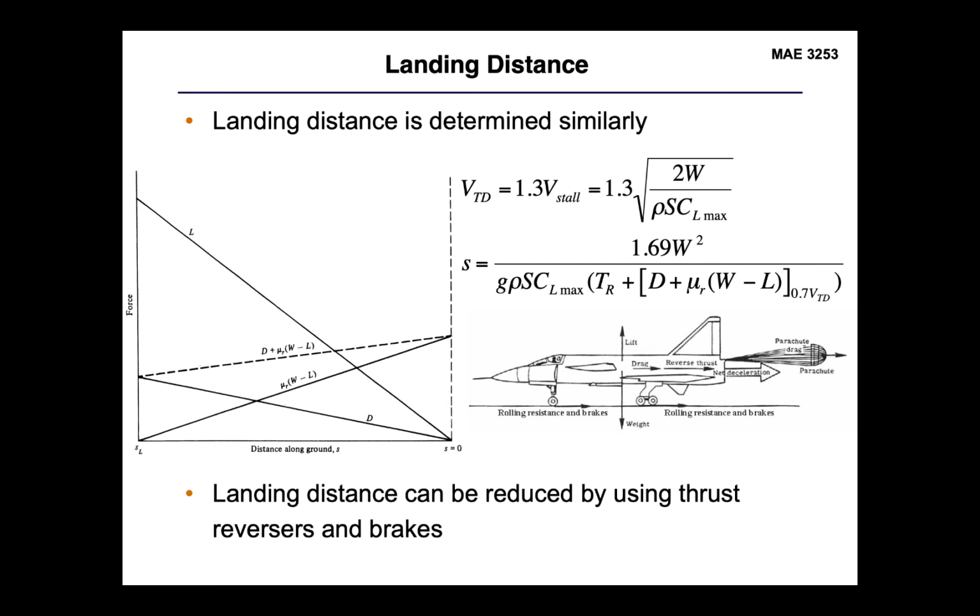deploying greater control surfaces. Typically our flaps are going to be deflected to greater angles for landing configurations. That's going to provide us a lower stall velocity, but we want to have a little bit greater margin, so that gives us a larger cushion in case we need to abort our landing procedure. So this gives us more wiggle room, as we're reducing the thrust on our aircraft and the ground is slowly getting closer and closer to our aircraft, or really the other way around, we have greater flexibility in being able to abort, and we don't have something nasty happen to us like we saw with the A320.